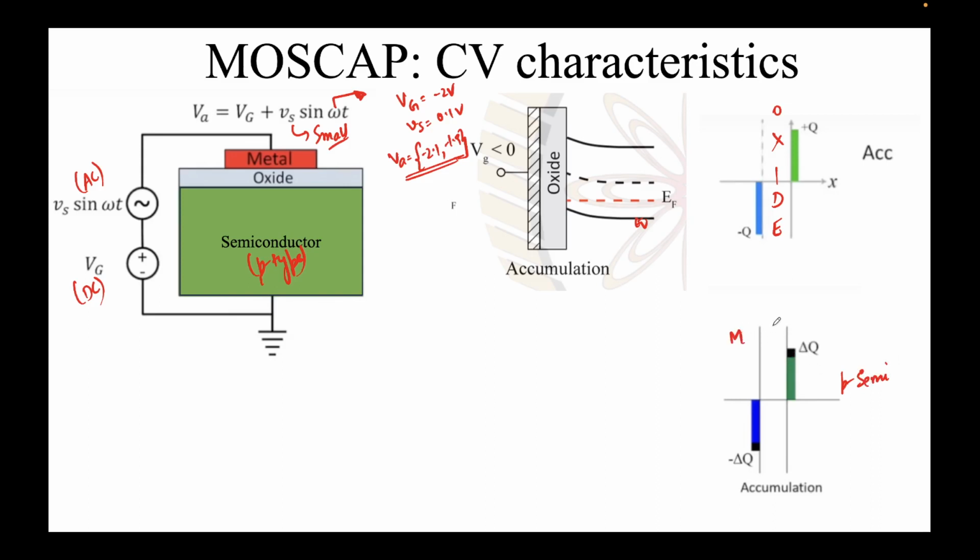This is metal oxide semiconductor. And what you're seeing here, and again, I'd like you to recall that C equals dQ over dV. The differential expression for capacitance is this. So you're changing a voltage. What you're changing is Vs. Vg remains constant. Vs is the thing that we are changing, right? And dQ is, you measure this Q somehow, all right?